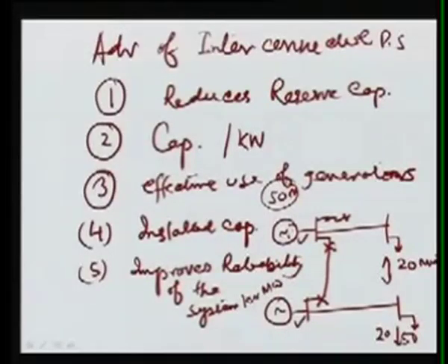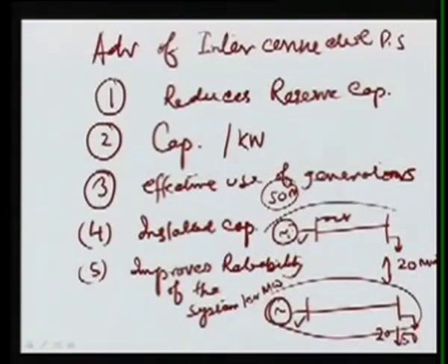We should have a very fast and reliable protecting device so that we can trip here. We can trip this line, and we cannot allow this fault to propagate and transmit in this zone. But if we assume there is no interconnection here and the fault occurs here, this system will be intact and we can maintain the power supply in this system, and both are operating in